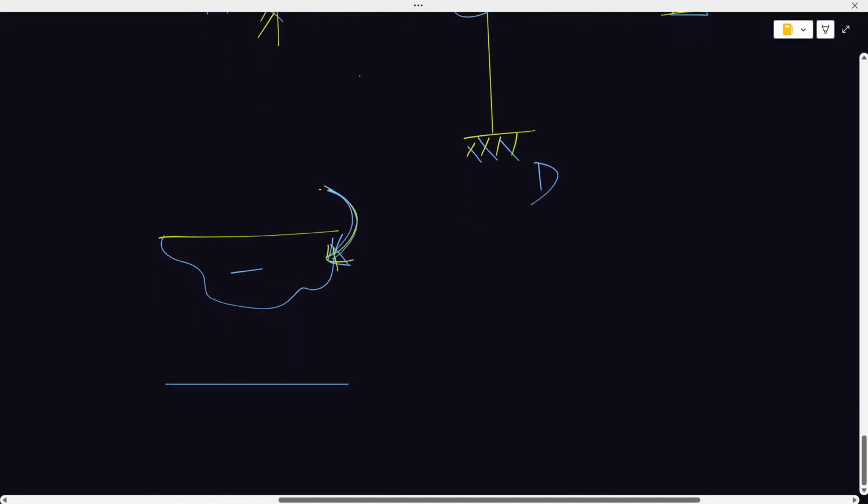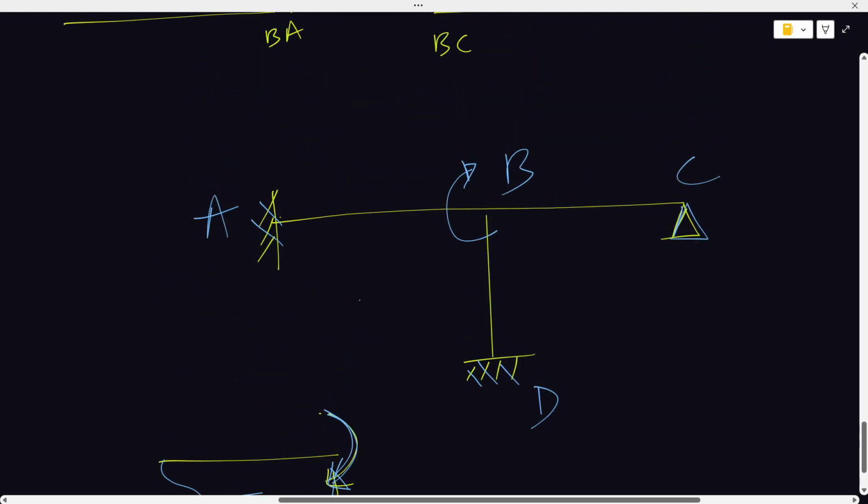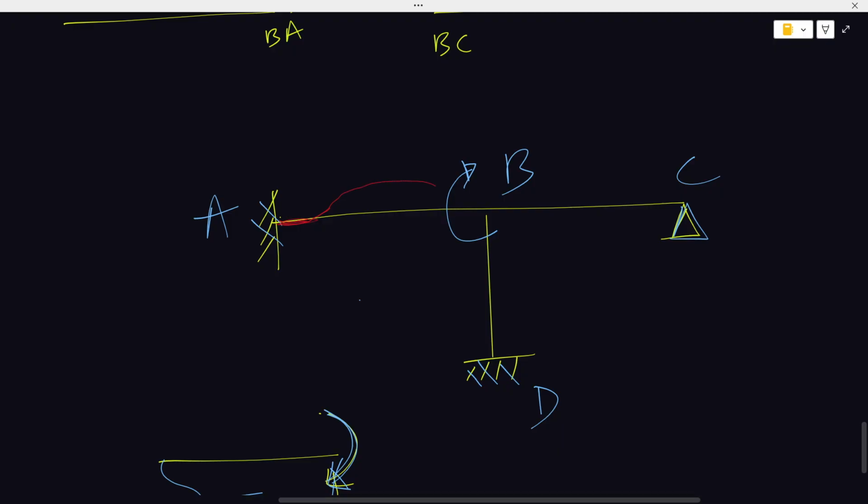Since we're having negative moment, we'll be having a frowning face. For the elastic curve, I'll be using red. Because of the no slope condition, I can move horizontally, then proceed.